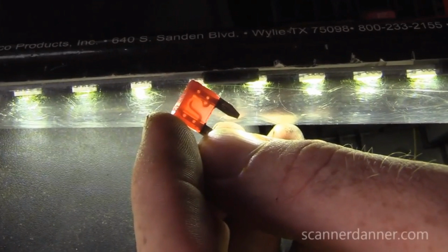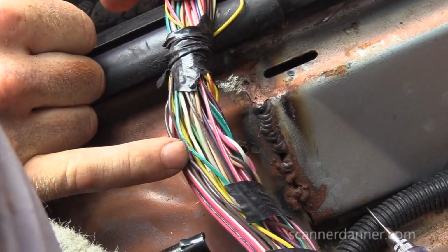The answer with this car is not to just plug in a new fuse and give it back to the customer. We have a blown fuse. The case study addresses that. We go through some short to ground testing. This car was in an accident. This is about an hour and 20-minute video. Caleb and I were pulling our hair out trying to find this short to ground. We couldn't find it. And then we did some detective work. We looked at the fenders on the front of the car, and the lines were not right.